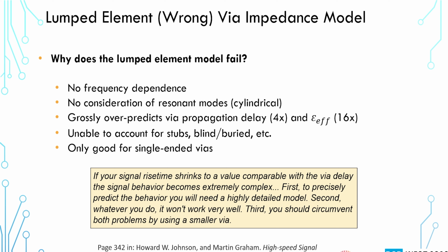There's no frequency dependence, as I mentioned before, and we should reasonably expect some frequency dependence just given the capacitive and inductive nature of vias. There's no consideration of any sort of resonant modes. It grossly overpredicts the via propagation delay, and in fact, if you just plug in some numbers into the propagation delay, you'll see that it really grossly overpredicts what the propagation delay should be.